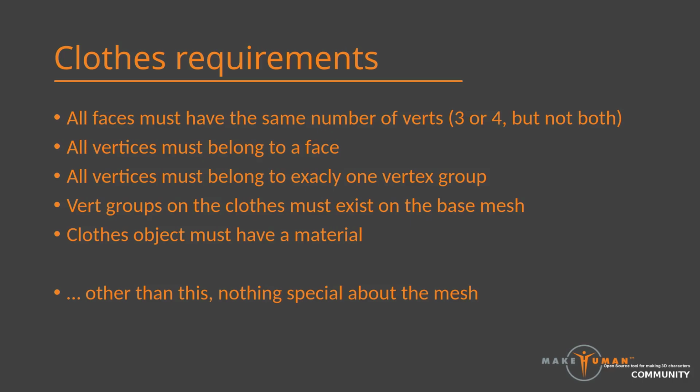Outside that, you cannot have loose vertices hanging around not belonging to a face. The rest we just saw. You need a vertex group and a material. The vertex group needs to also exist on the human mesh. But with this fulfilled, you could use any mesh as clothes.